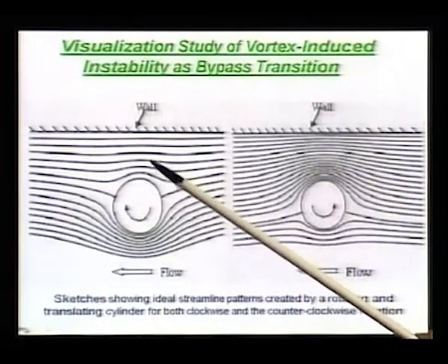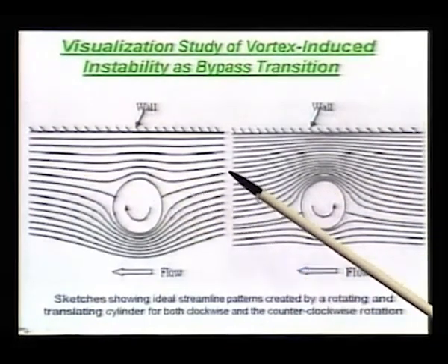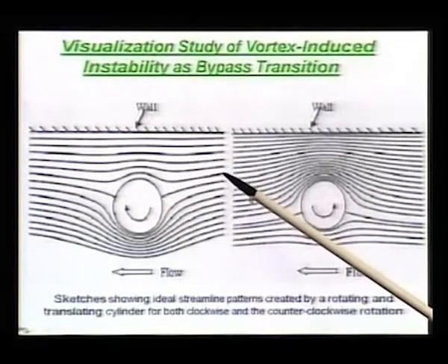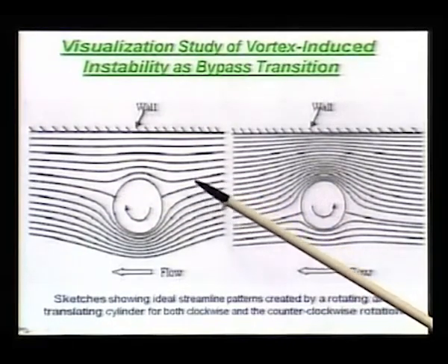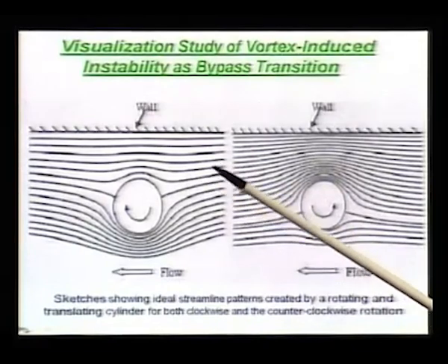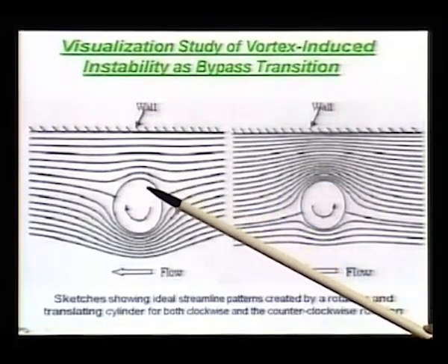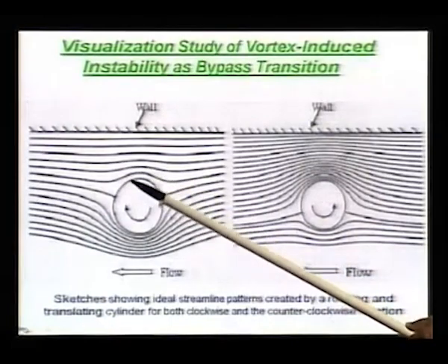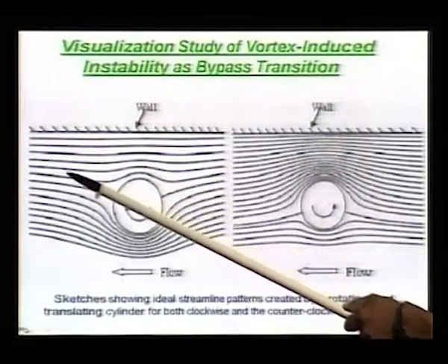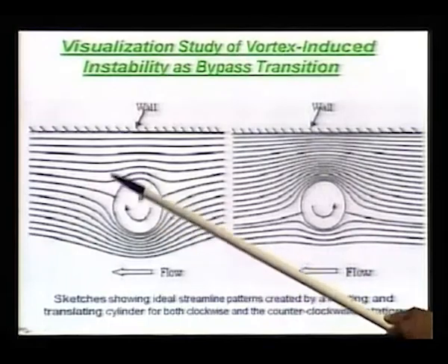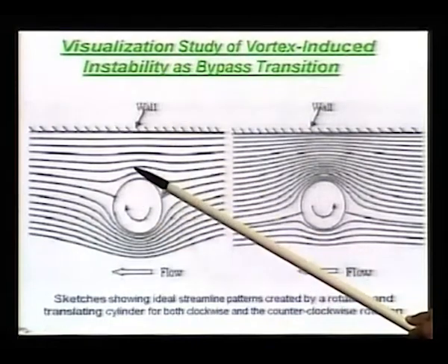That is given by the streamline curvature, and here you see a very interesting feature. You start off with the adverse pressure gradient, but more or less with a similar divergence, that is followed by a favorable pressure gradient, again followed by a rapid adverse pressure gradient, and again followed by favorable pressure gradient. So, whatever damage that can occur only here.